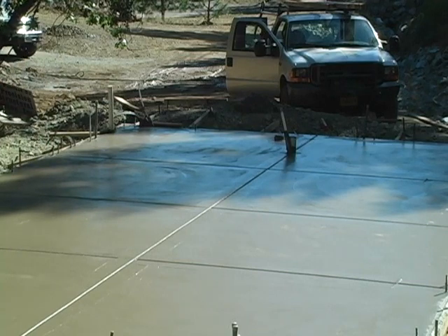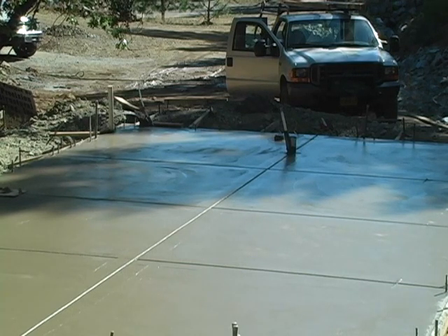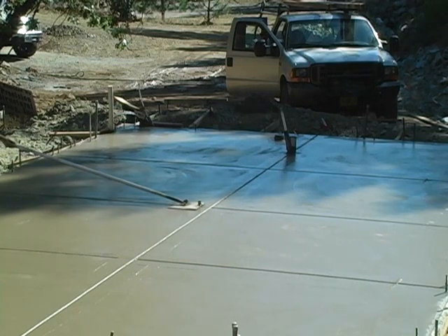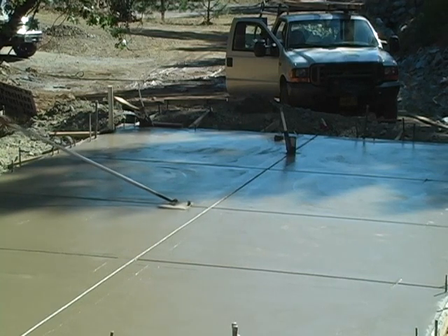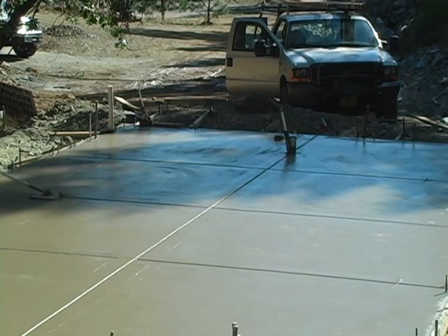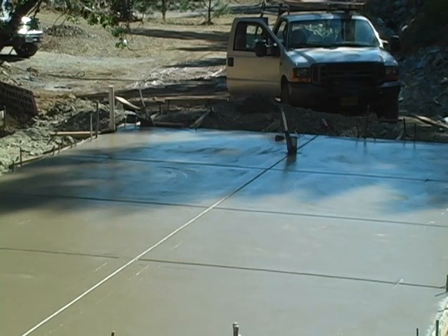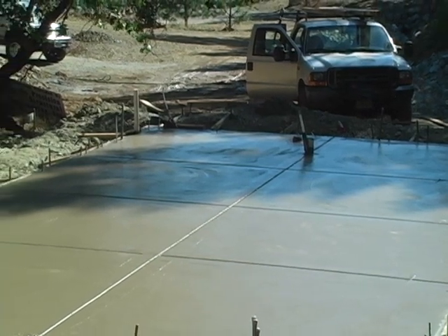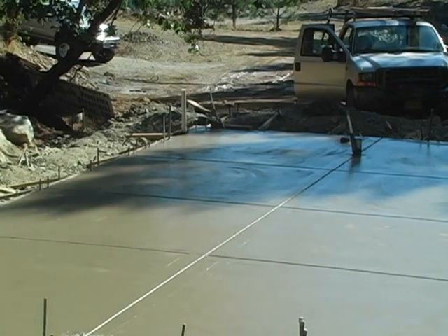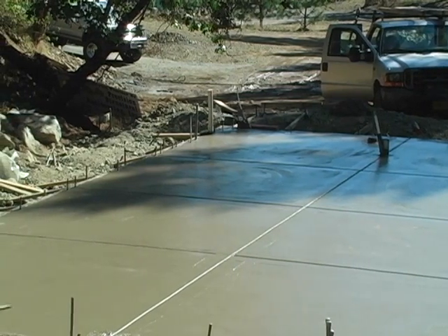You can see as he lifts the grooving tool out of the groove, he doesn't just pick it up. He'll actually put it in at an angle, push it, tilt it, pull it back at an angle. So watch here, the tilt goes up and tilts it back, and then as he comes out, he can either pull it out at that angle like that or tilt it back up the other direction and pull it out. If you just try to lift it out of the groove or pull it straight out the back to the forms, again, you'll get a mess of concrete all around the area where you did your lift out.